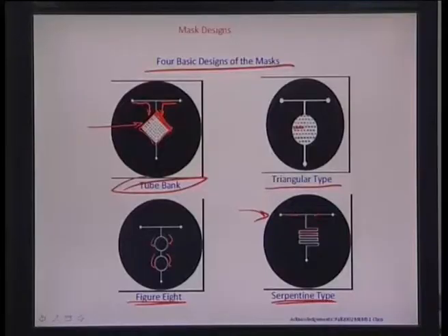Similarly, here if you see in this particular example, you have let us say flows coming from both ends here and mixing along this circular area, which is essentially made up of small triangular pieces of resist, and if you just do the replication on the top of this, it becomes triangular pieces of PDMS pillars on the top surface of the reservoir, which is shown here in this particular example.